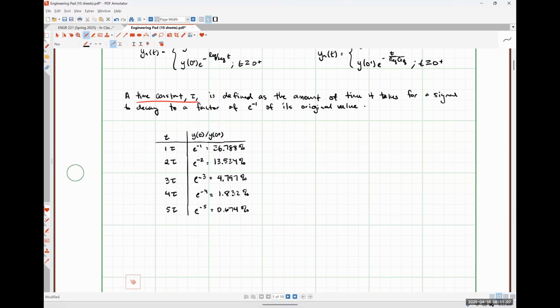So as far as we are concerned in this class, 5 tau is simply the length of infinity, and that's going to change for every given circuit, depending on what values of resistance, inductance, and capacitance that circuit has. So this essentially tells us how long we need to allow this circuit to either discharge, or as we'll find out in a couple of moments, charge in order to hit some steady state value. Okay.